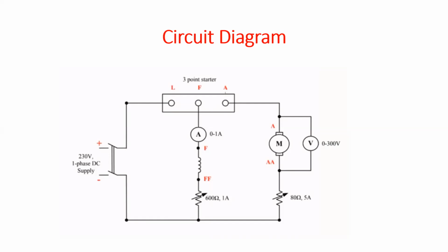In modern types of drives, we are using electronic control, power electronic control. So we have SCRs, silicon controlled rectifiers, MOSFETs, IGBTs. We can control the voltage with the help of controlled converters. With the help of these controlled converters, you can apply a gradual increase in voltage from 0 volts to maximum volts. And that is referred to as a soft start, because the applied voltage is gradually increasing. So you are starting the motor with a slow speed. Otherwise, if the initial current is very high, it will start with a high current. So I hope you understood the concept of this starter, soft start.